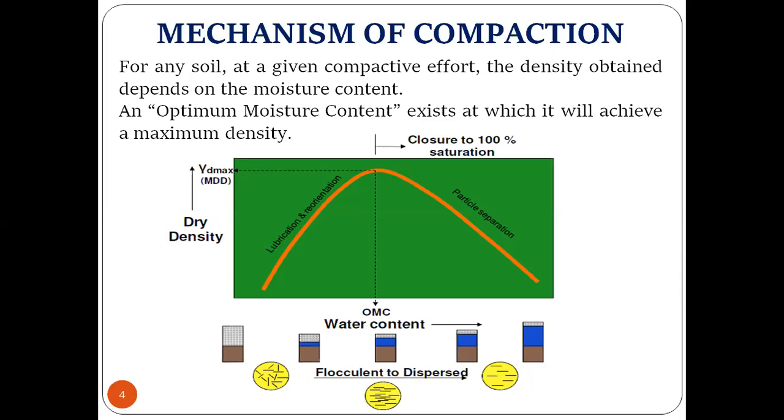The same thing happens here. When we add water content, the dry density will be more, so more air will be expelled out. You can see in this curve that when I add water, the density goes on increasing. That means the soil becomes denser up to some point.